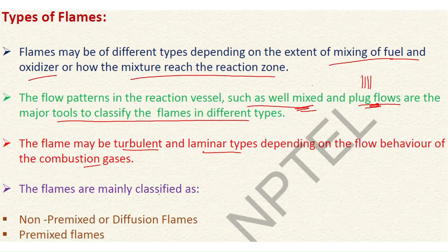The flames are mainly classified as non-premixed or diffusion flames, and premixed flames. Premixed is where the fuel and oxidizer get mixed completely with each other before the reaction, and non-premixed is where the mixing of the fuel and oxidizer does not happen before the reaction.